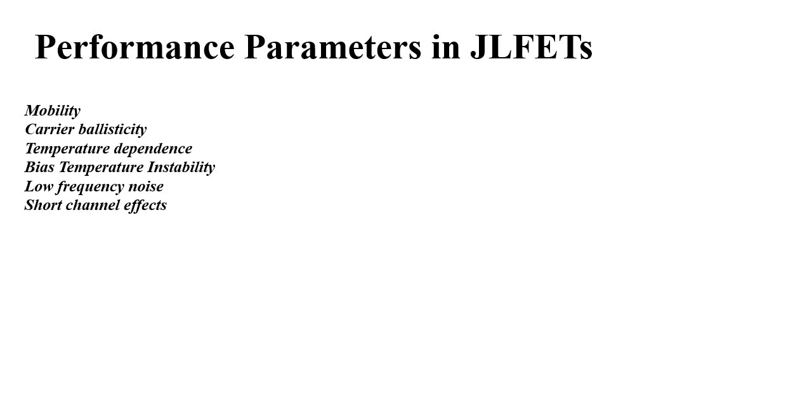Now we will see the performance parameters in the junctionless FETs. First is mobility. Now it has bulk conduction, so the mobility in the junctionless FETs is degraded.